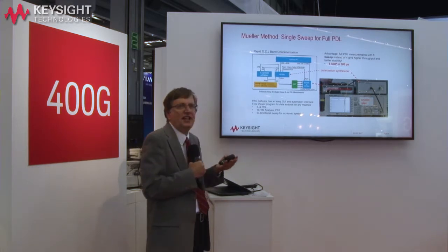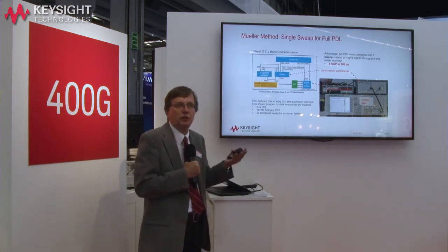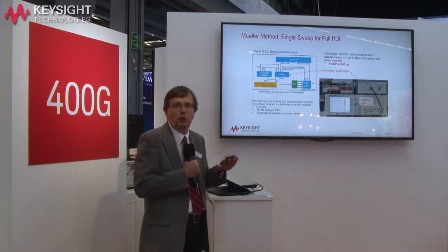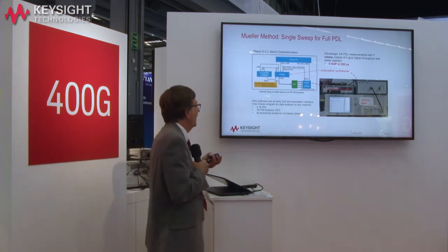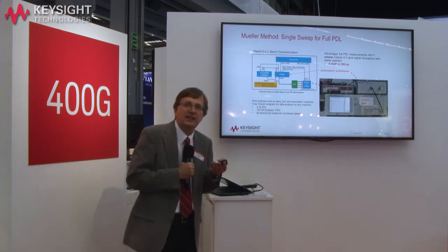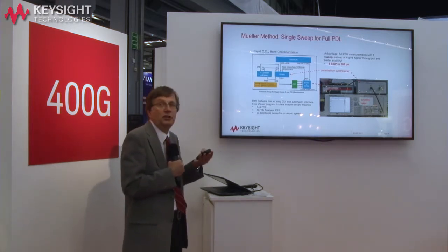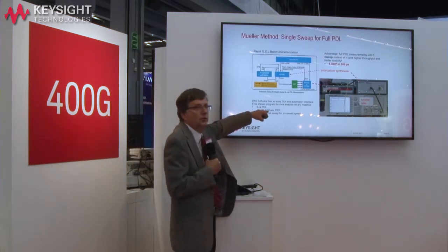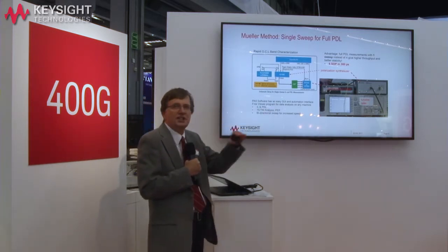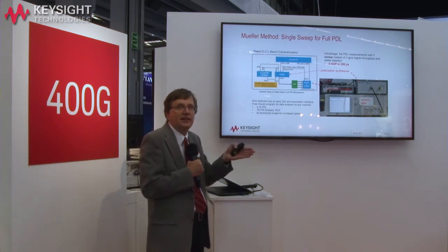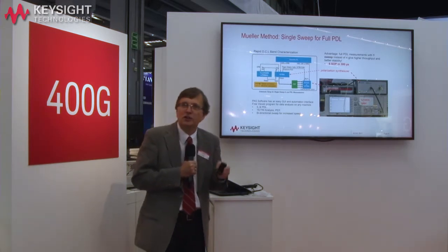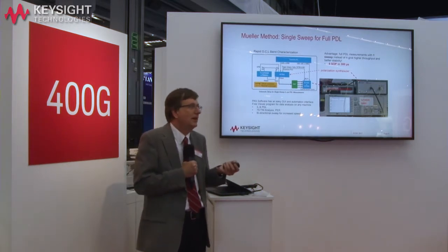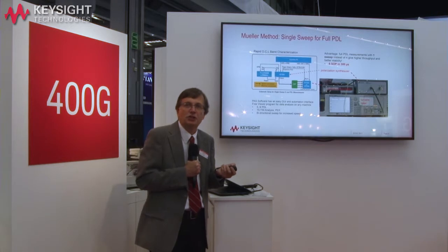So we're very stable against any kind of temperature drift or vibration because the whole measurement is made in less than a millisecond for the polarization dependence. And that again gives us the Mueller matrix that we use for calculating polarization dependence. And we can also use that to analyze what the spectrum looks like in the 2 main axes without having to go through the effort of making that alignment. And that's what turns out to be very useful now when we do wafer measurements.